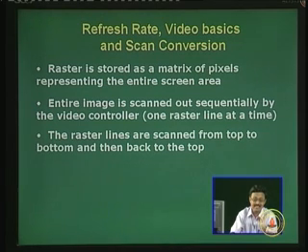Unlike the DVST, both the random scan and the raster scan display systems have one thing in common: the persistence of the phosphor is too low. It will vanish in no time. It is about 10 to maximum a few hundred, not even 100, maximum 100 microseconds. So, the pixel has to be visited again, otherwise it will switch on and off too early for you to have a consistent view. Flicker-free display is what we want, and to do that we know that we have to do a refresh, so the refresh word is still there. But the raster has come in.